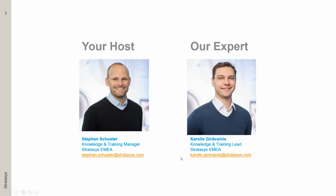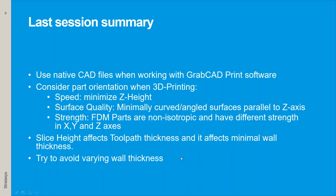But before we jump in, let me give you a brief summary of the last session. Carolus, please jump in if I misunderstood something, but try to be short. What we learned is that with GrabCAD Print, we can use native CAD files when working and when printing, and we always recommend to do so, because then all the STL conversions are done automatically by the software and don't need to be done manually, or the settings don't need to be set.